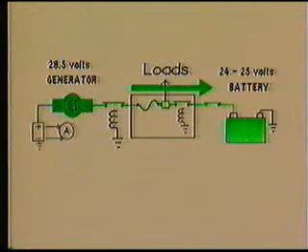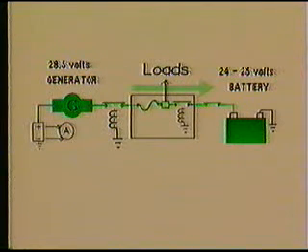As current flows into the battery, the power provided by this current is stored in the battery. As the battery approaches its full storage capacity, the stabilized voltage of the battery will increase. This reduces the difference between the battery voltage and the generator voltage, which will cause the current flowing into the battery to decrease. In actual application, the current flowing from the generator into the battery will never totally stop, but will become extremely small as the battery approaches full charge.